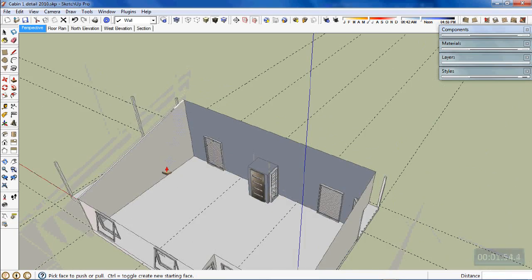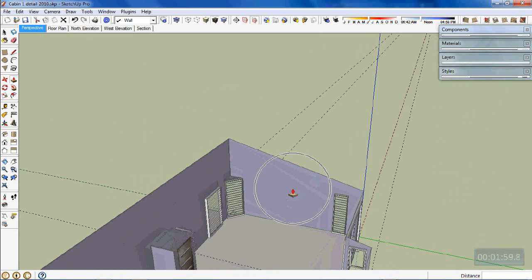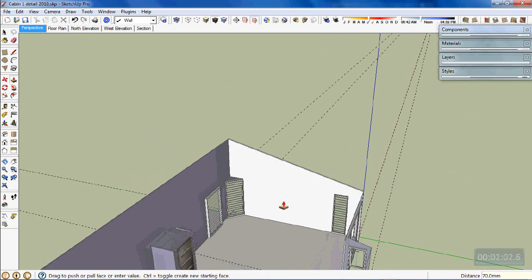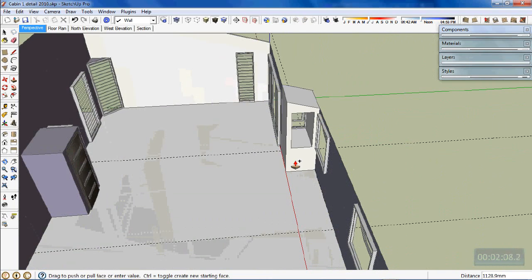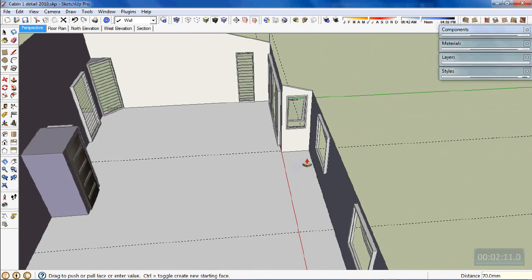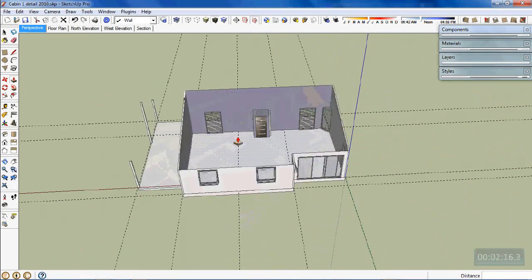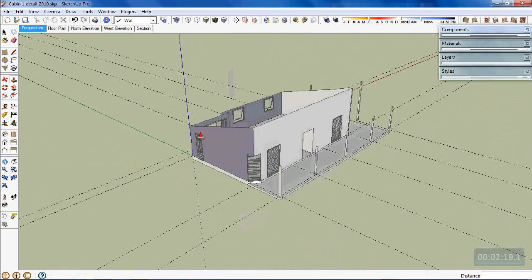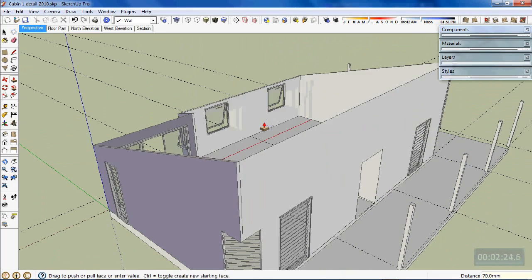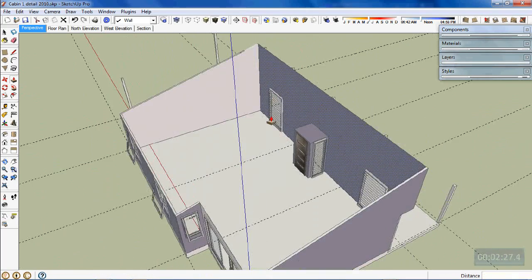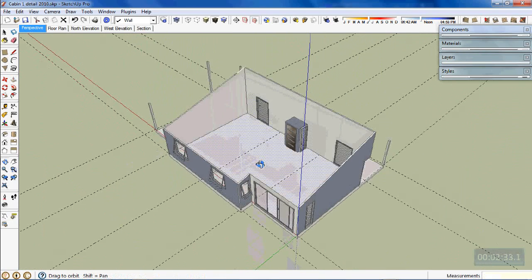Now I'll do that to the gabled ends of the building probably first, doesn't really matter. Come in by 70. Let me do, for instance, this one. Come in by 70. Each time with the push-pull, I'm pressing and releasing the control key. Right, so that's those. Now I'll do this face of the building, plus key, so control key to get plus, and 70. And what do we do this one now? And 70 there. Okay, now that's missing this one.